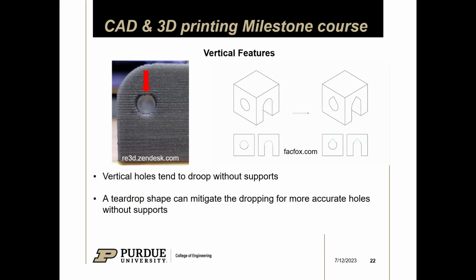It's completely parallel to the build surface. So that's a 90-degree overhang or a bridge, right? And then as you go farther and farther away, it might be 60 degrees, 70 degrees, until you meet the sides, which is 90 degrees, or I guess zero. So you can see here on this model, the top of the hole is drooping a little bit.